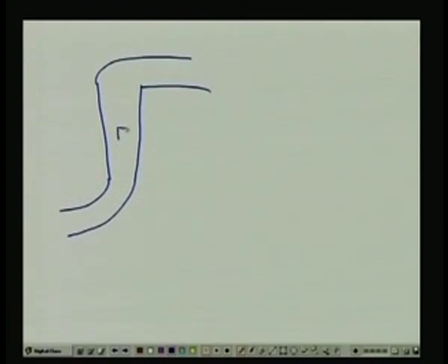You see here, the liquid is flowing through this. So, what is this annular area? As you move up, what will happen? The area of cross section, leaving the float aside, will increase; it is always increasing as you go up. The area of cross section of the float is the same. So, the annular area, which is the shaded area, will change as this float goes up.